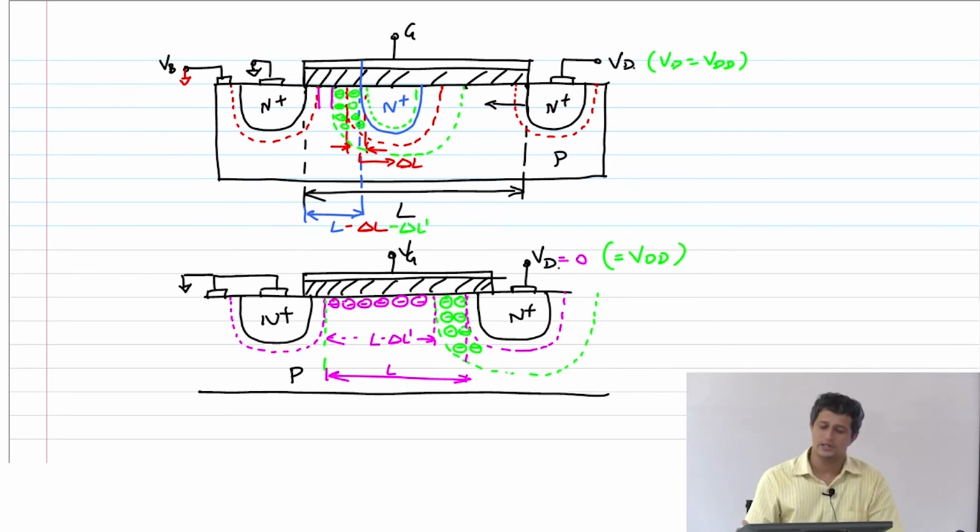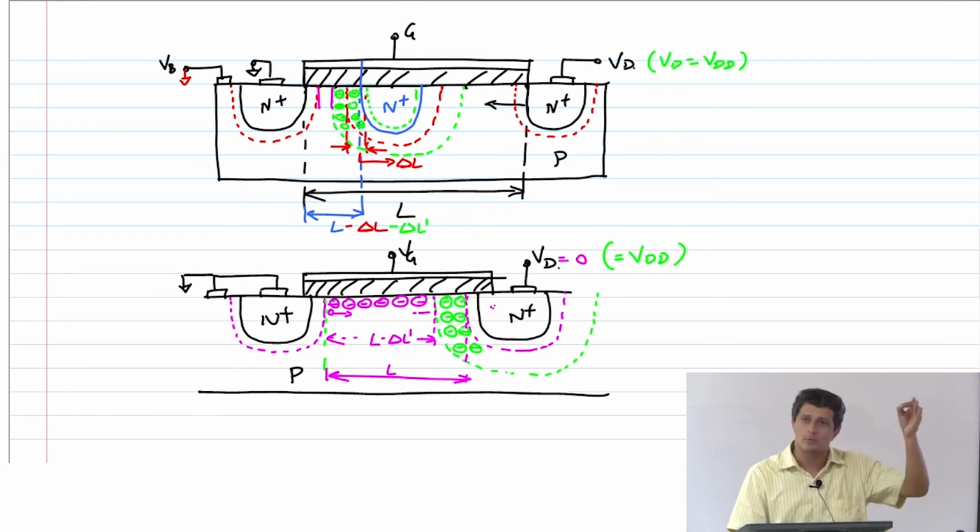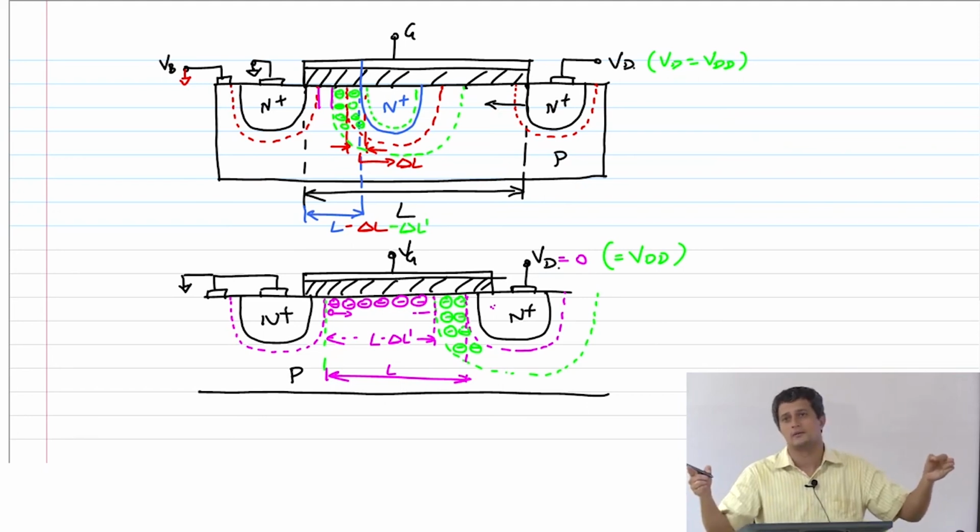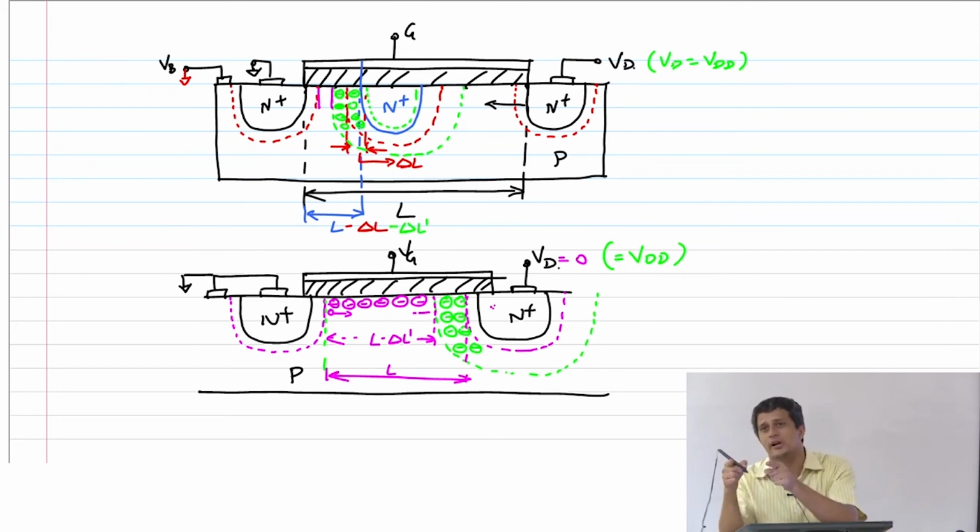Yeah, so what happens is, previously when we derived the equation, all we did was to ensure that the electron had to basically go through this region, reach up to here. It had to go from source to drain, right? That was the net L. But now remember that in the depletion region, the electric field is so high that once it gets there, it will get to the other side very easily. So you are effectively trying to accelerate the electron only in this channel region.